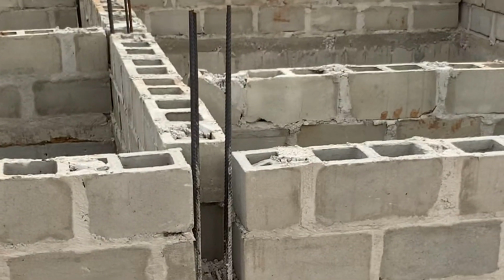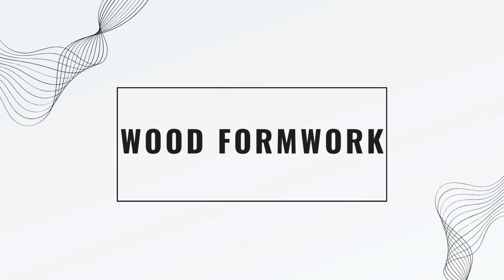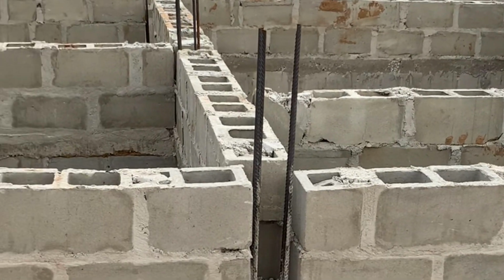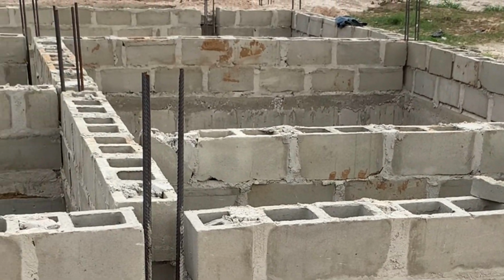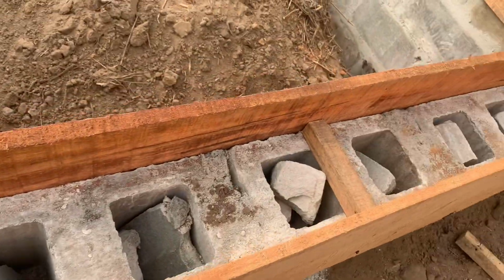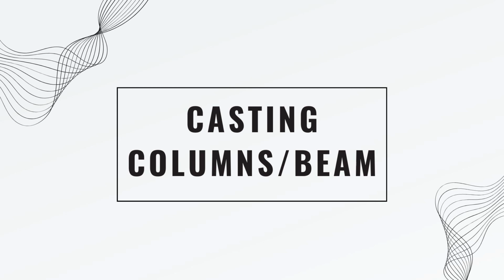After taking the block work to the DPC level, it is time to start the wood formwork. You will need to look out for a very good professional carpenter to start budging the space between the starter columns and the block work. Please ensure that the formwork are done properly to avoid wastage of concrete during casting or pouring of the mixed concrete. Now, the next stage is what we call casting of the starter columns.